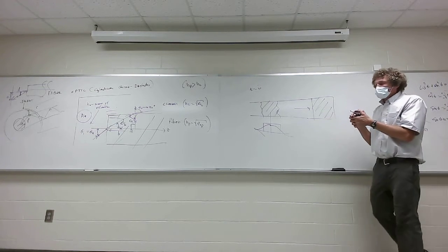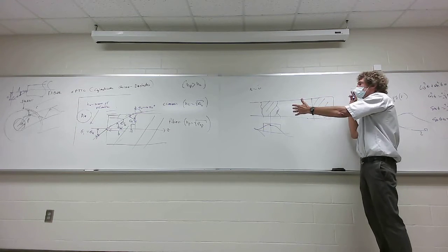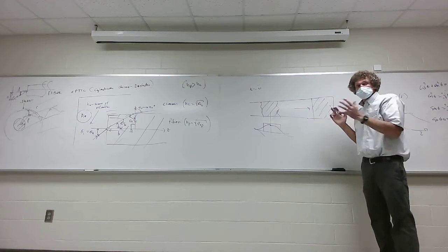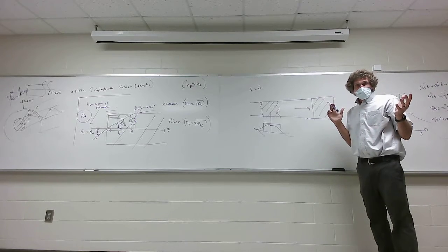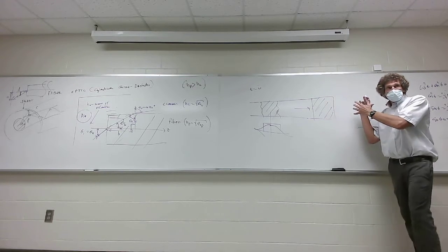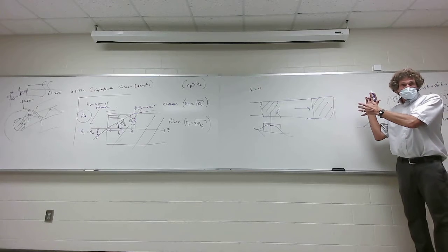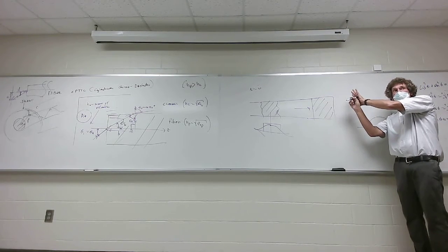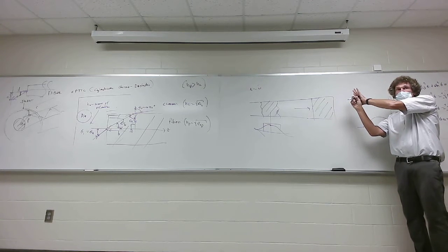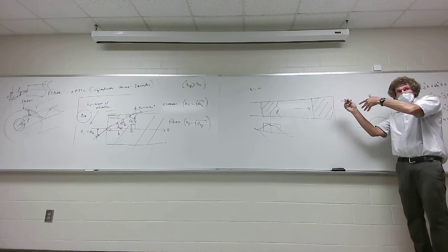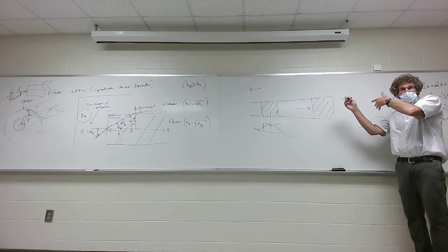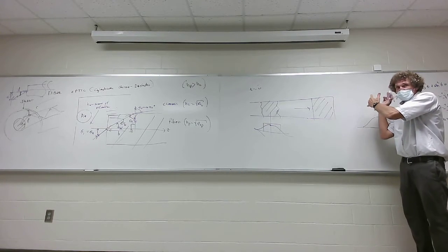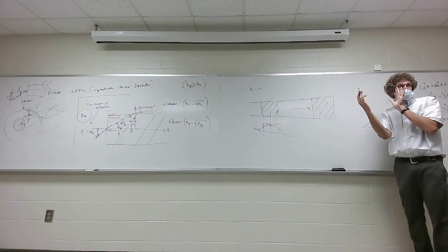So what they normally do is, they figure out the maximum distance that they can have a fiber optic tube, and this is true fiber now, before they need what's called a repeater. You don't know the term repeater? What it'll do is it'll take this and then it will convert whatever comes in into a 1 or a 0, and it knows what's being sent before it, and then it will sharpen up the signal and resend it. So all that blurring goes away and it starts afresh again.